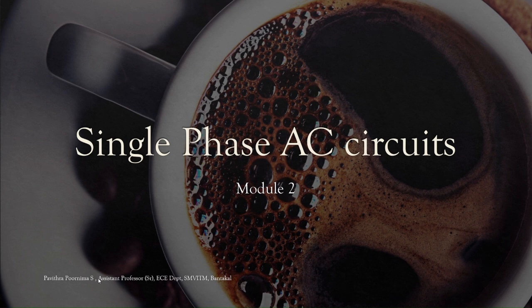The single phase voltage in India is commonly 230 volt and the frequency is 50 hertz. In single phase representation, we represent voltage as V equal to Vm sin omega t and current as I equal to Im sin omega t. So we'll discuss in this video pure R, pure L and pure C circuits.